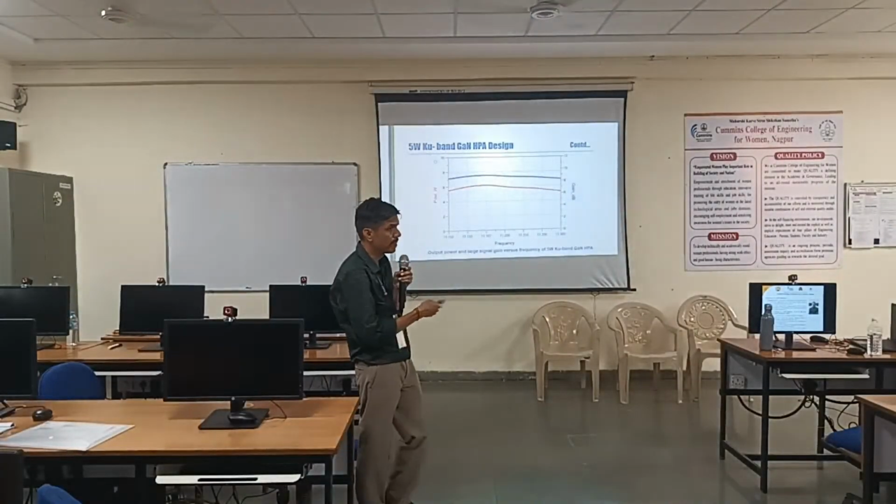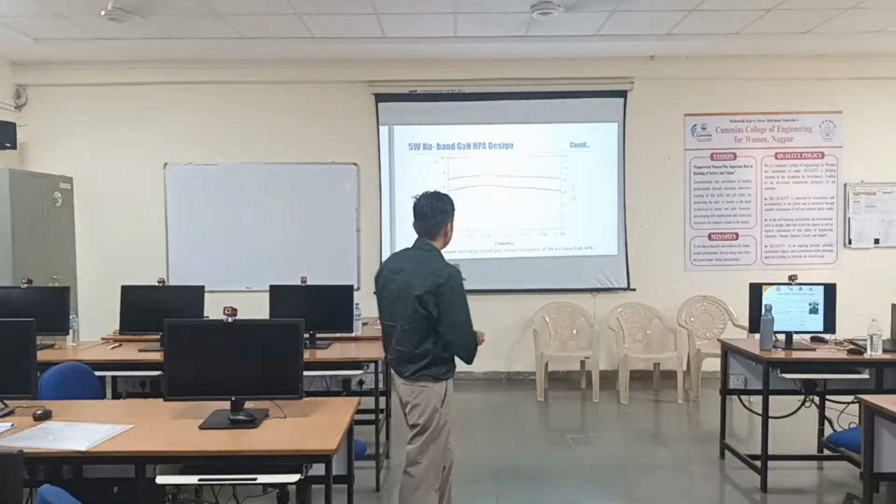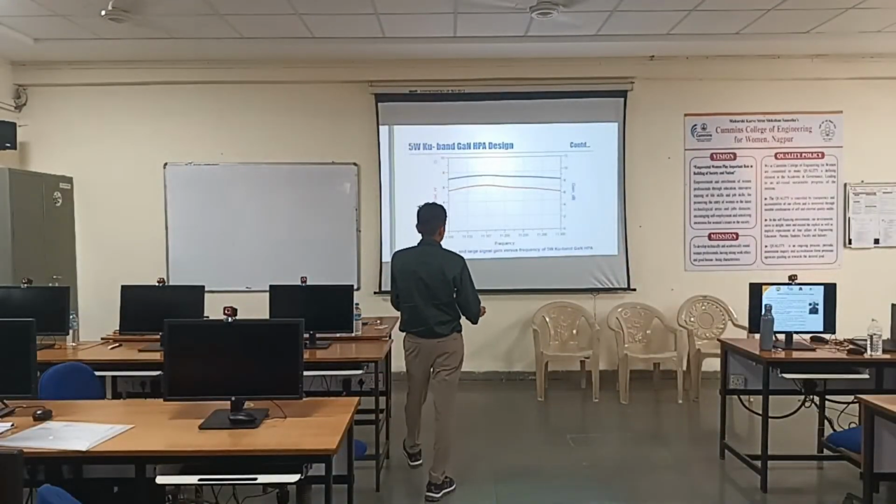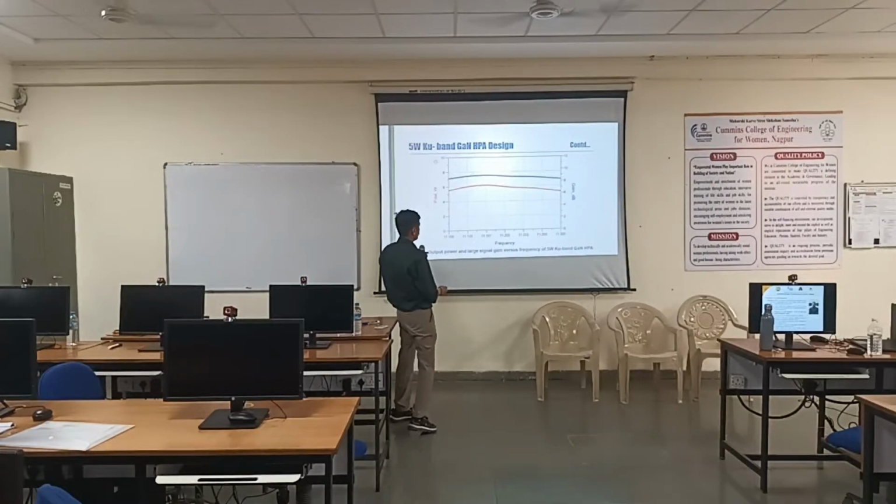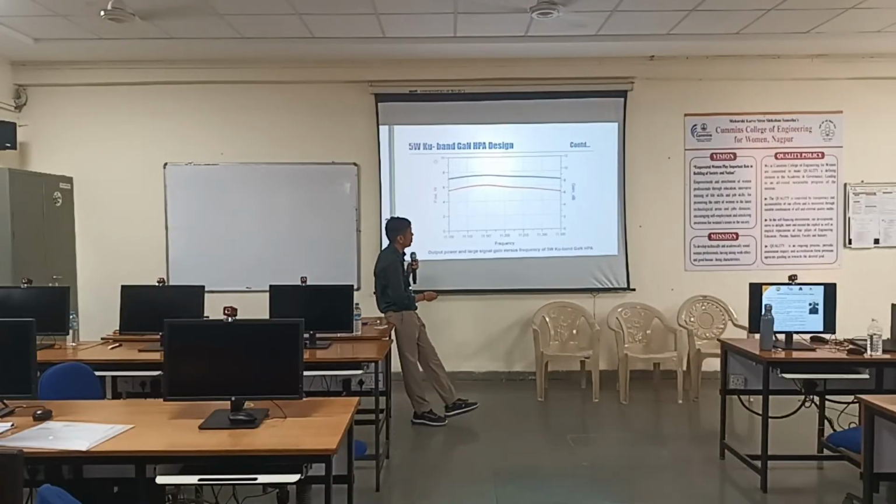Then this is the in-band response. Because we said that we want the center frequency 11.200 and it should work from 11.150 to 11.250. Still I have plotted from 11,100 megahertz to 11,300 megahertz. This is the band of 200 megahertz.